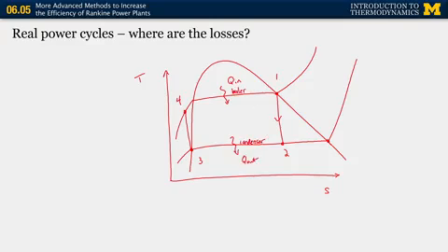And the primary way that we're going to see a loss in the boiler and the condenser is in the form of drop of pressure. So we're going to lose some of that pressure at the high pressure condition. So if we were to draw the actual process here, it might be something more like this. So this would be the exit of the boiler with losses. And this is what they call pressure head, so we'll lose some of the operating pressure associated with the boiler.